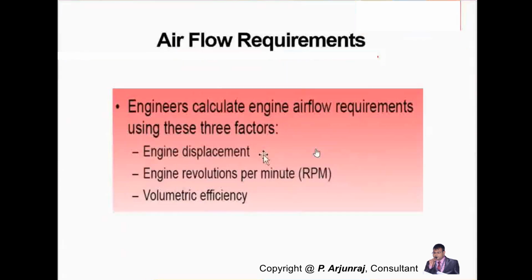And you know how to calculate the engine displacement, which is nothing but pi by 4 D squared L, where D is the diameter and L is the stroke length, and you know the engine RPM, or at what speed the engine is operating, and you know the volumetric efficiency. Okay, how much is the mass flow rate over here, which is inducted into the system to get out the theoretical mass.